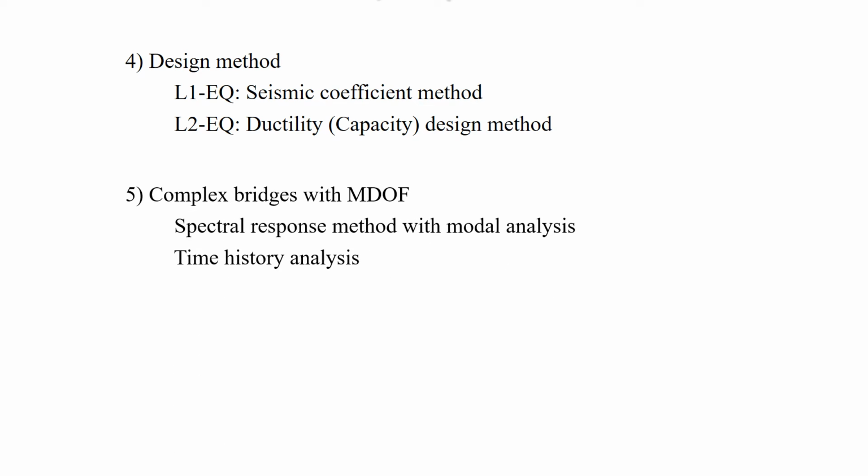5. If bridges have a complex structural form with MDOF, such as arch bridges and cable-stayed bridges, more sophisticated design methods are applied, such as spectral response method with modal analysis and time history analysis.